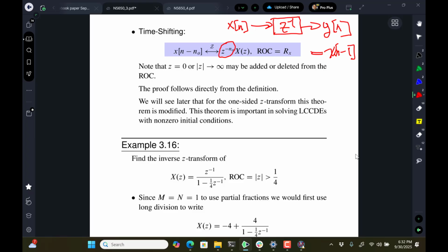You can put anything inside the block, but if you're doing, say, an FPGA implementation, you would prefer to put in the individual delay blocks rather than z to the minus 10, meaning a 10-sample delay. You'd want to be able to count the fact that you have to have 10 registers to hold it.